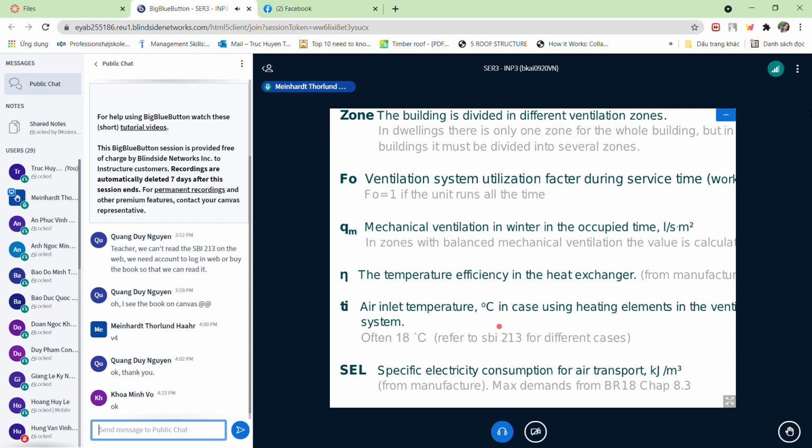But in reality, the manufacturer can't really control this one, because if you design a ventilation system in a building with really long ducts, or really tight ducts with small radius or small areas, your system is going to use more energy to get the air out to the rooms. So this is something you as a designer need to be aware of.